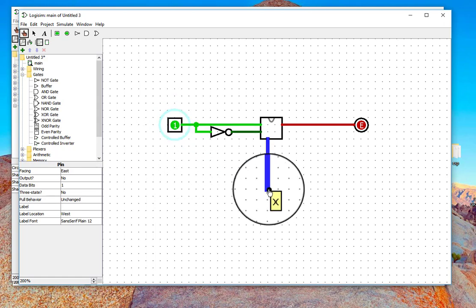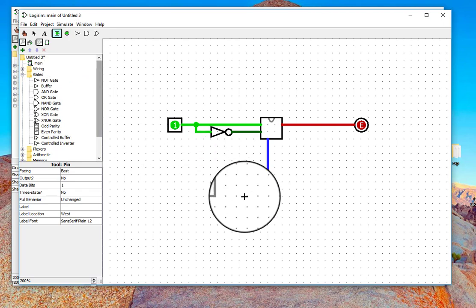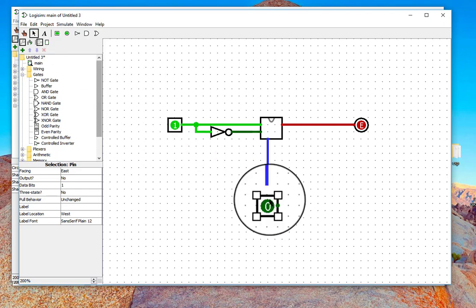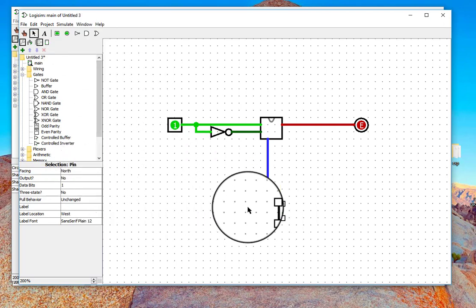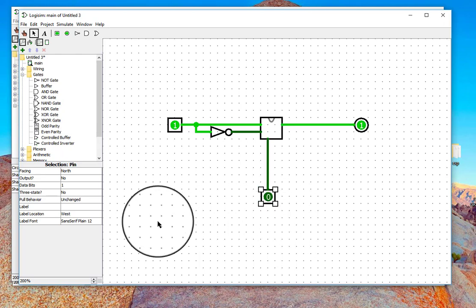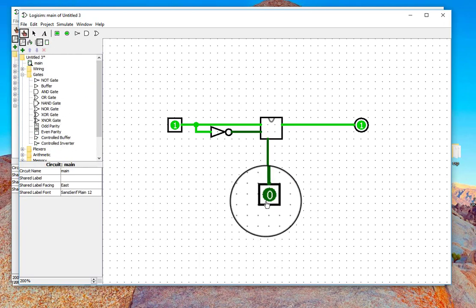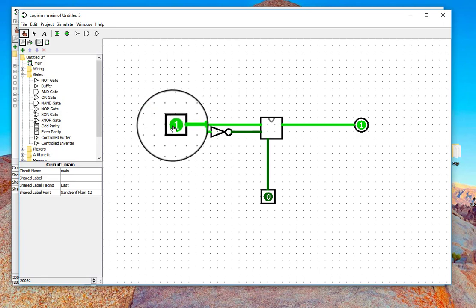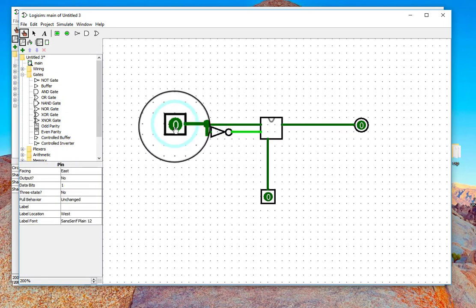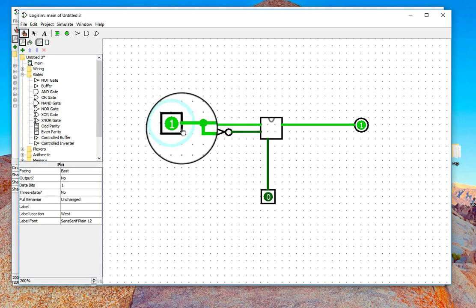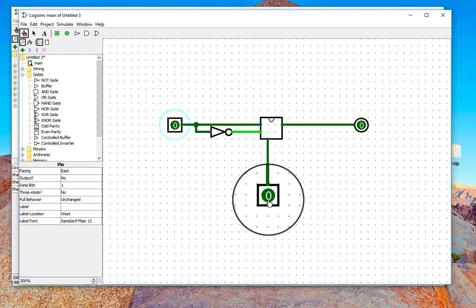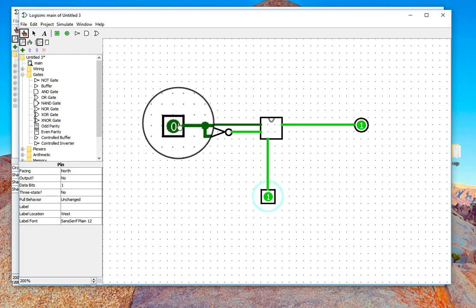So what I'll do here in my control, plug that in. Now in my simulation, if I say channel 0, watch this. Input's a 1, output's a 1. Input's a 0. Notice the input and output exactly match. If I turn this into a 1, notice the input and output are now opposite one another.